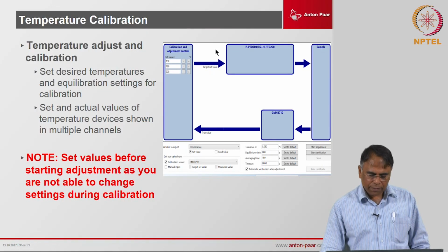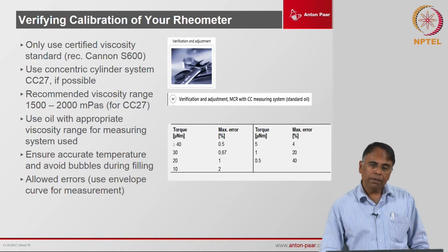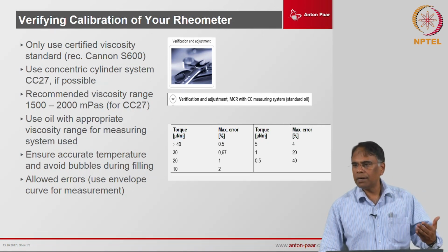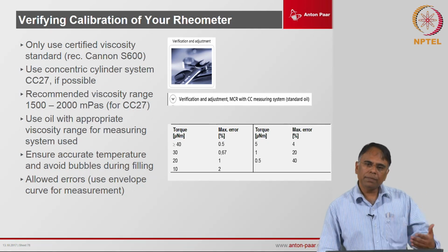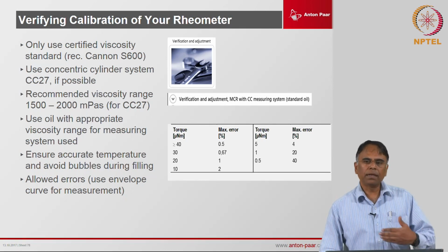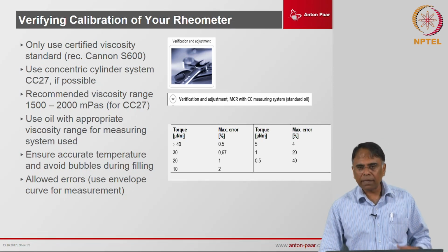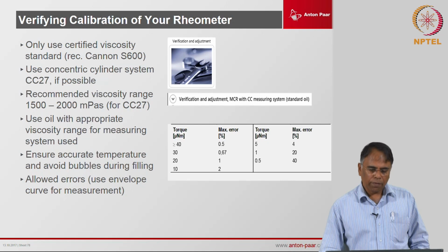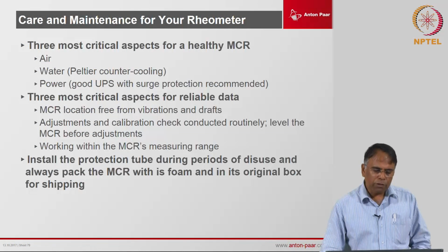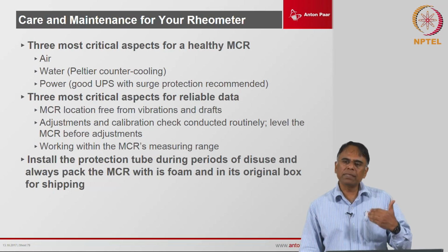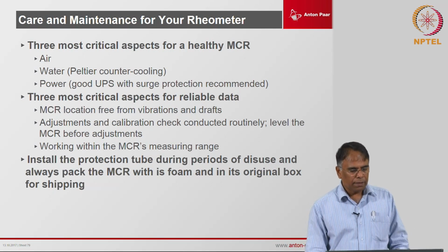Temperature calibration is important, it has to be done at least once in a year, and always cross check with either a standard oil or a standard reference material like a PDMS, which has certain known values. Okay. So, just to check that your measurements are really in the right place. Okay. So, this is something which also needs to be done on a regular basis. I would recommend that we do the measurements at least once in 3 months or once in 6 months.